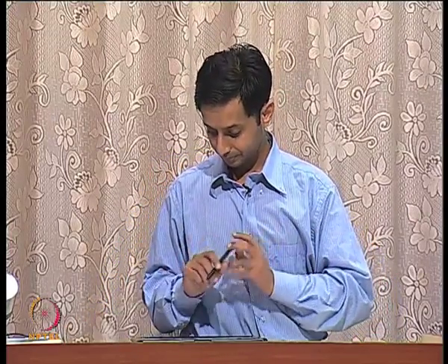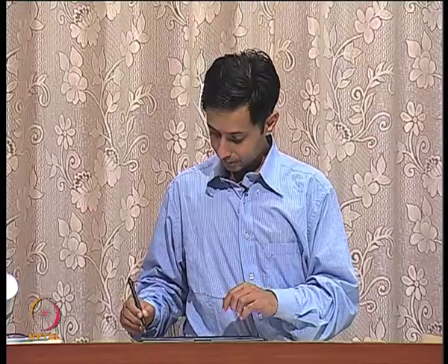It also has distributed resistance. It also has distributed capacitance. If the capacitance were not there, then I could lump both the inductance and the resistance, because all of these come in series and they add up nicely. But because there is the capacitance, you can't do that.